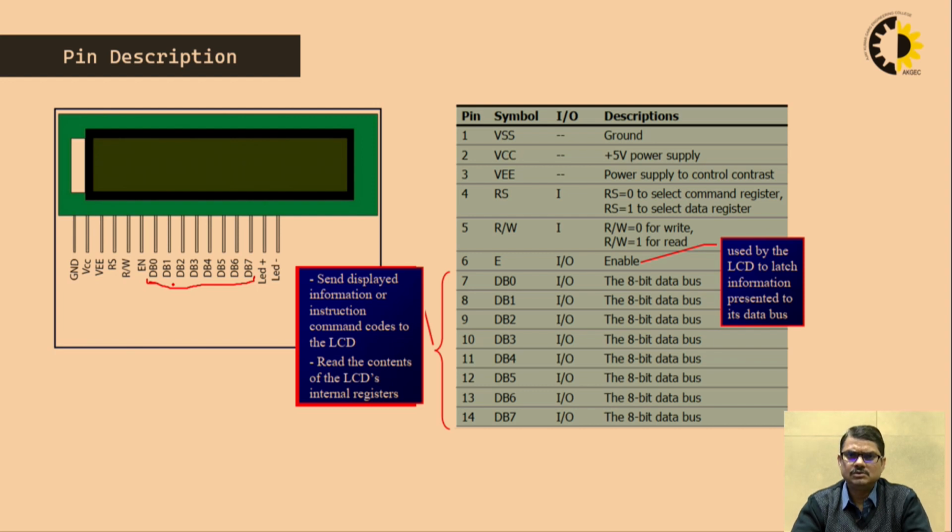And it is good to say that our microcontroller in this scope is the 8051, which is also an 8-bit microcontroller. Very easily we can output the 8-bit data. This is the simplest way of interfacing an LCD with any microcontroller.